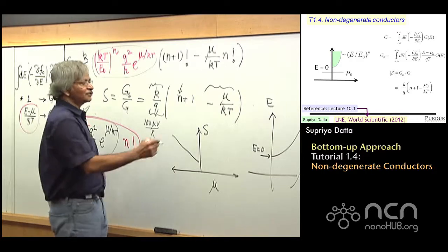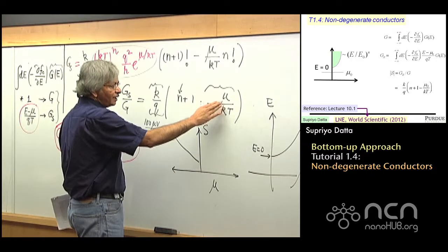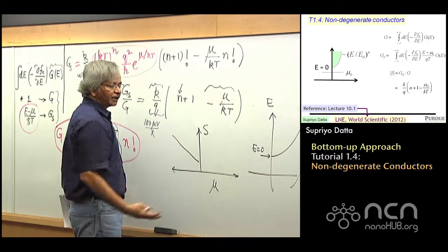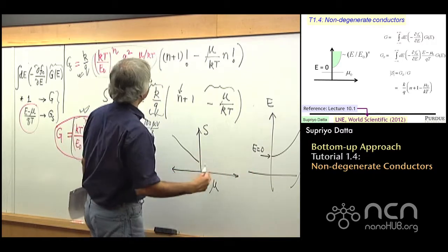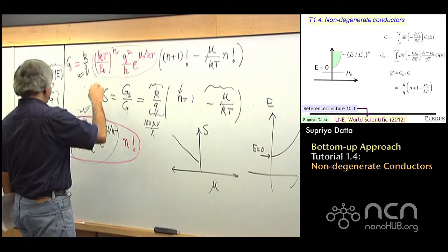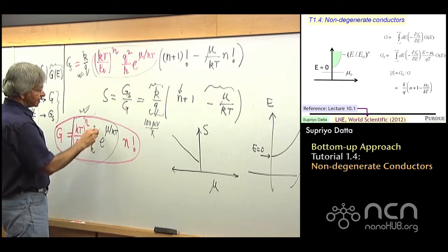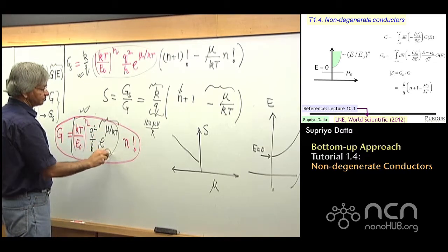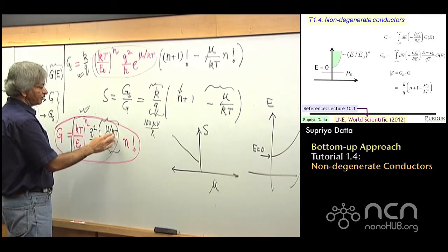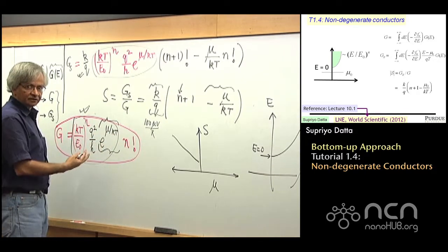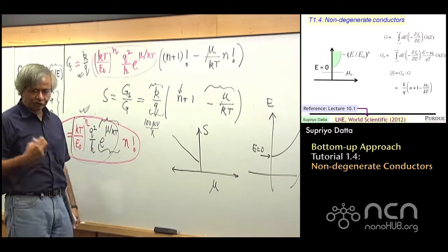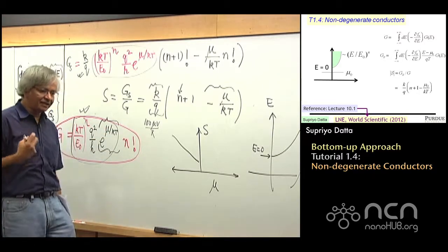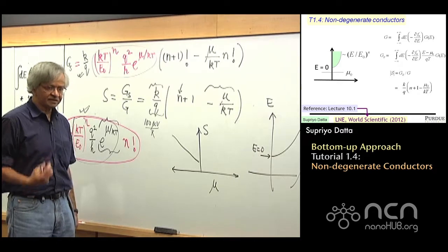Well, if it is indeed that big, it won't conduct very well, because the conductance itself would go down significantly. If you look at the expression for conductance, there's an exponential of mu over kt there, and if this is a big negative number, you don't have much conductance left. So overall, yes, this might act like a voltage source, but with an extremely high resistance.